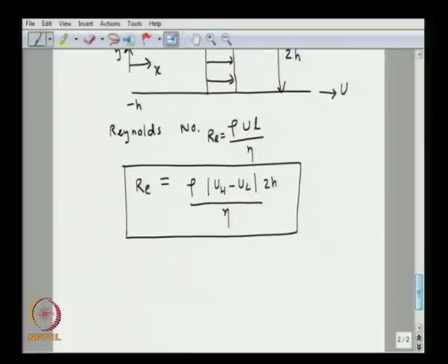It has been found that for Reynolds number less than 100, the velocity profile obtained by this model matches very well with that obtained from experiments. So, which is a case in microscale flow situation, quite often the Reynolds number would be less than 100. So, the analytical result obtained here for the Couette flow situation is applicable to microscale flow situation.